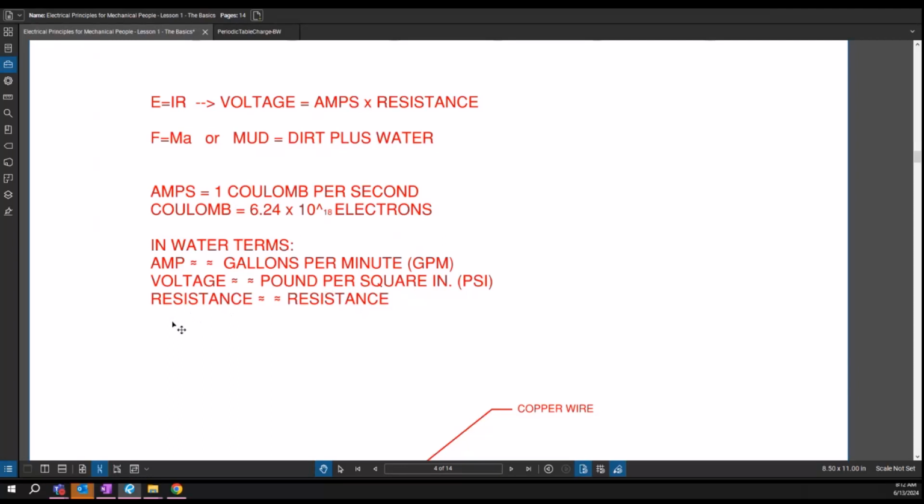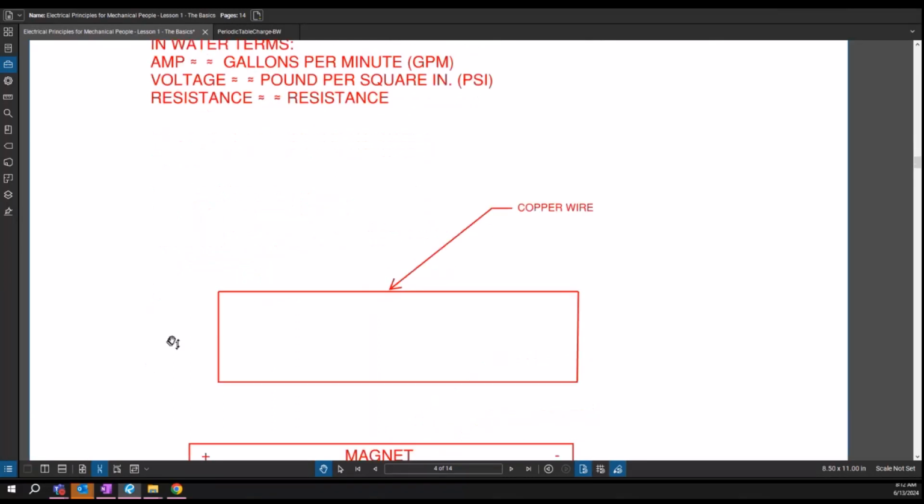right? Because if you have a water hose that is 2 miles long and you turn the water on at the faucet, 50 PSI at the faucet, you're not going to have 50 PSI at the end of the water hose. You will still have the volume of water, but you won't have the pressure of water. Does that make sense? Yeah. Okay, good. That's going to come into play in a little bit, and you will have to remember that because I've got a small test for you as we go, conceptually.